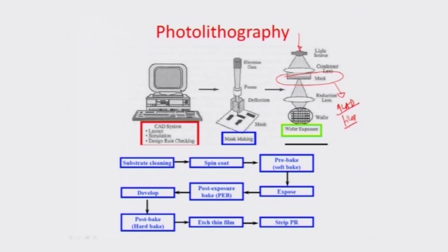The light falls onto the mask and passes through it; features made for blocking the light block those portions, and where features are open, light passes through and falls onto the wafer, which is coated with the photoresist. Thereby it creates imprints onto the top of the wafer, which you can develop later to formulate the features.